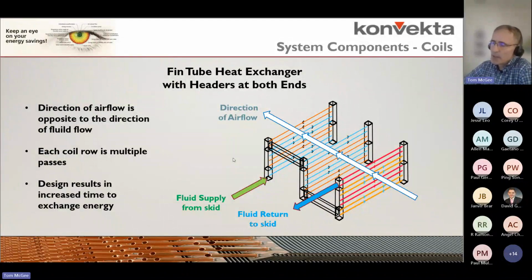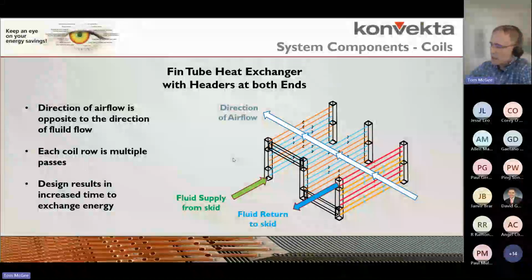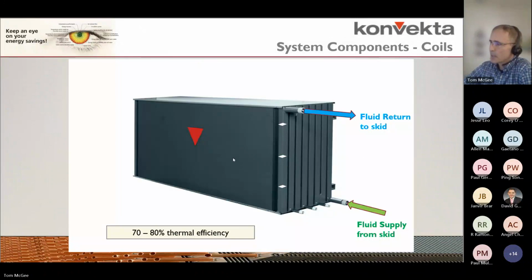So our approach temps are typically half or less than half of what you'd find with an off-the-shelf type of coil. And then this just shows that same concept. That's what our steel header looks like. You can see the lower right, the fluid inlet is the lower right connection, and then the upper left connection is the return. And then you see 3 drain lines.